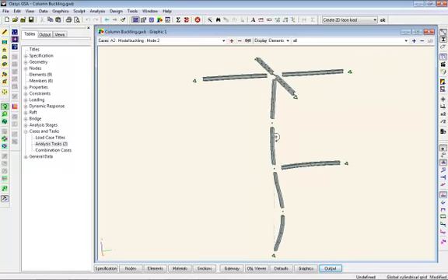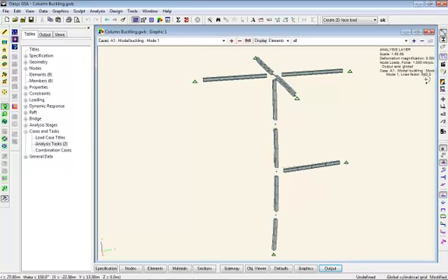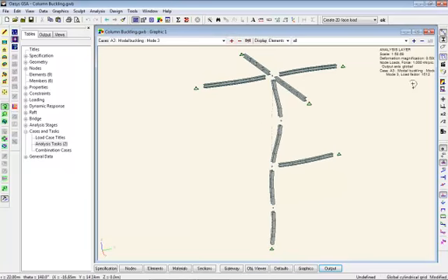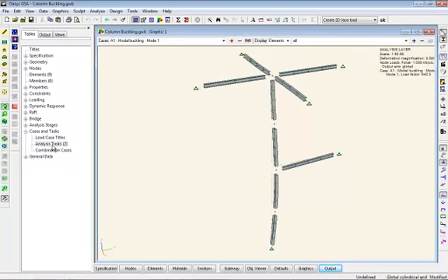Next mode, minor axis buckle. This time we're getting a load factor of 819, previous one 642, and of course you get the higher modes as well, 1500, 1900. Reality, of course, is the first mode will be the one which buckles first. Now, remember this 642 for the linear buckling.